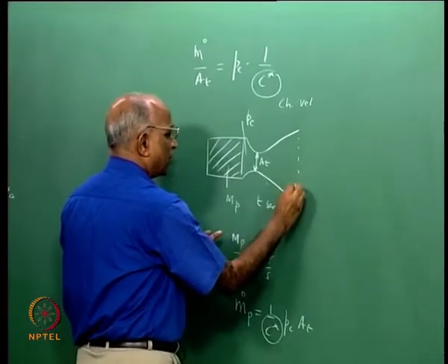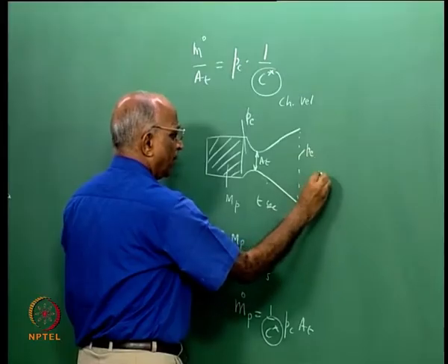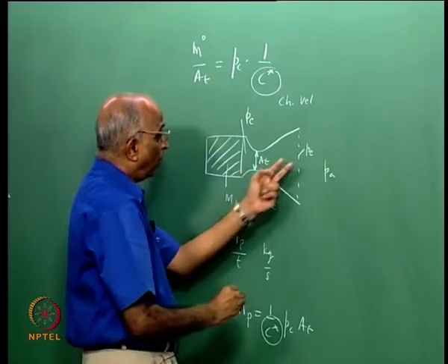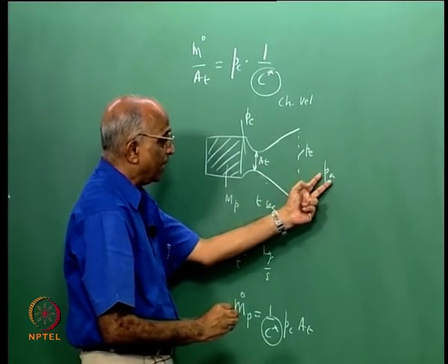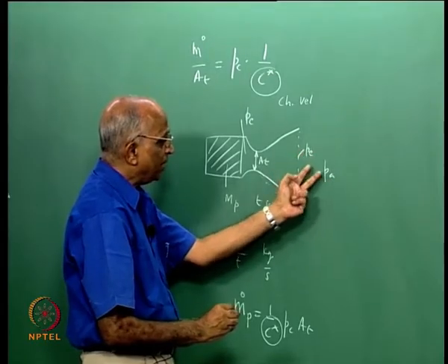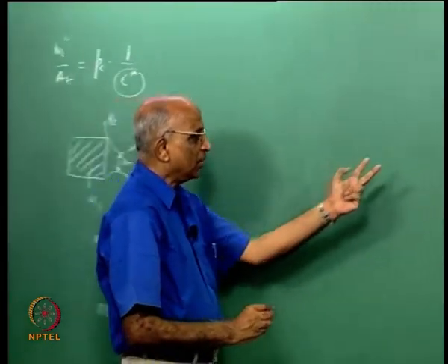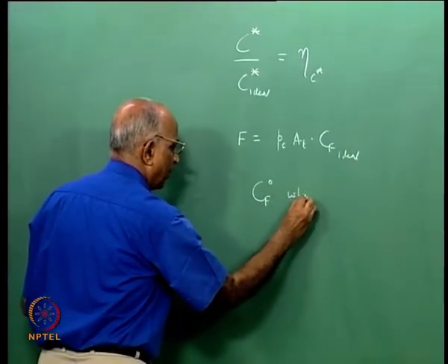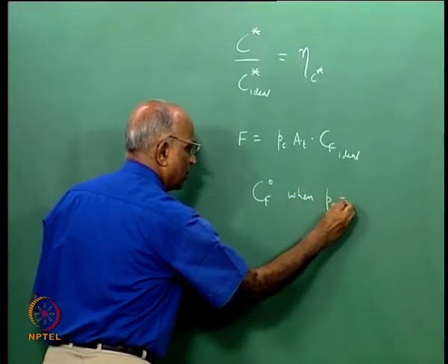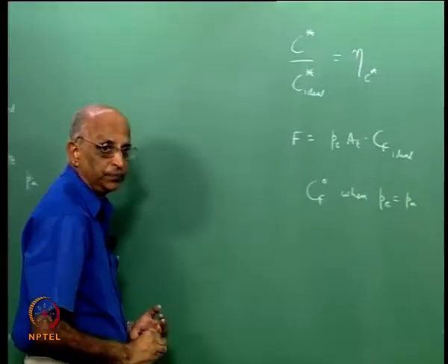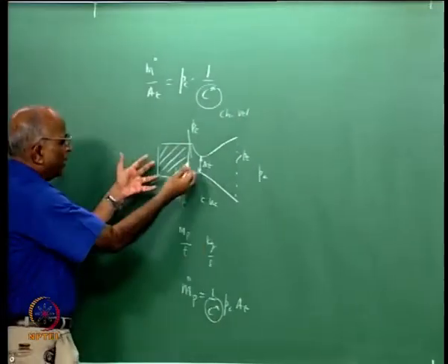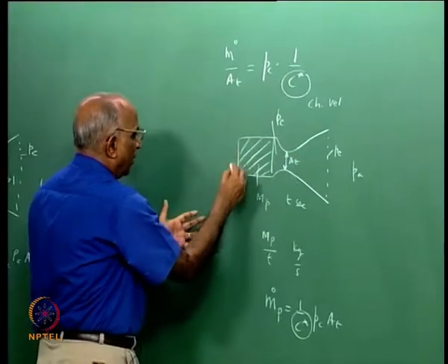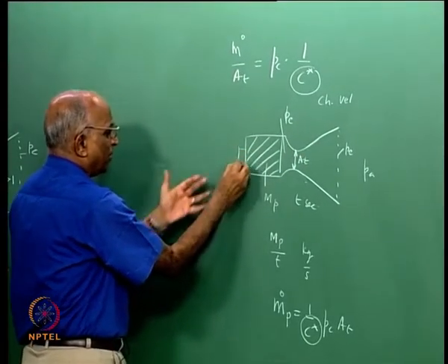That means always I have Pe here, I have the ambient pressure here, always Pe may not be equal to Pa, but the thrust is a maximum when Pe is equal to Pa. We called this ideal thrust coefficient Cf0 when the exit pressure was equal to Pa. Just the same way I have a rocket which is firing, I put some measurement here for a transducer.